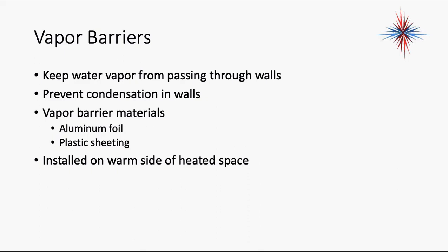It prevents vapor from building up between the insulation and the heated space. Again, I want you to think about that glass of cold water that I've used a couple times in discussion examples. You have a glass of ice water sitting on top of a counter in a warmer room, and all of a sudden I can be building up water vapor. You have your sheetrock.